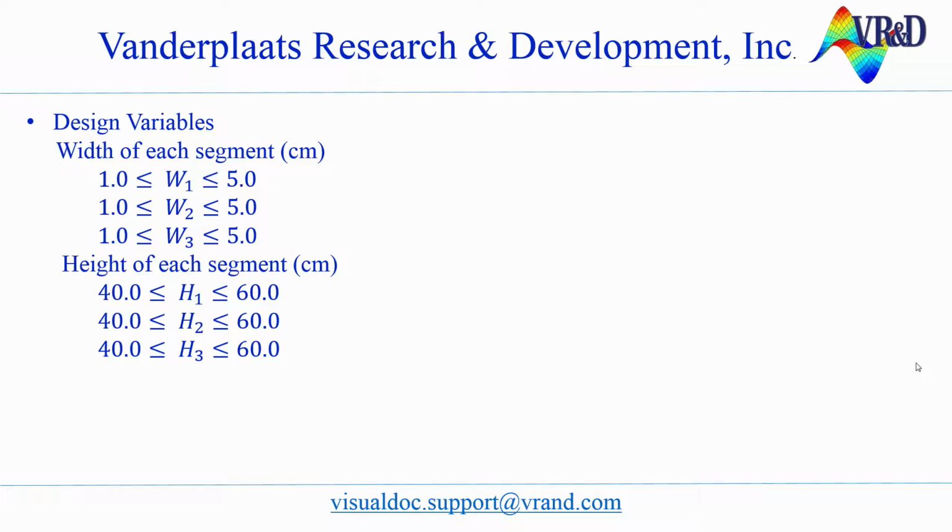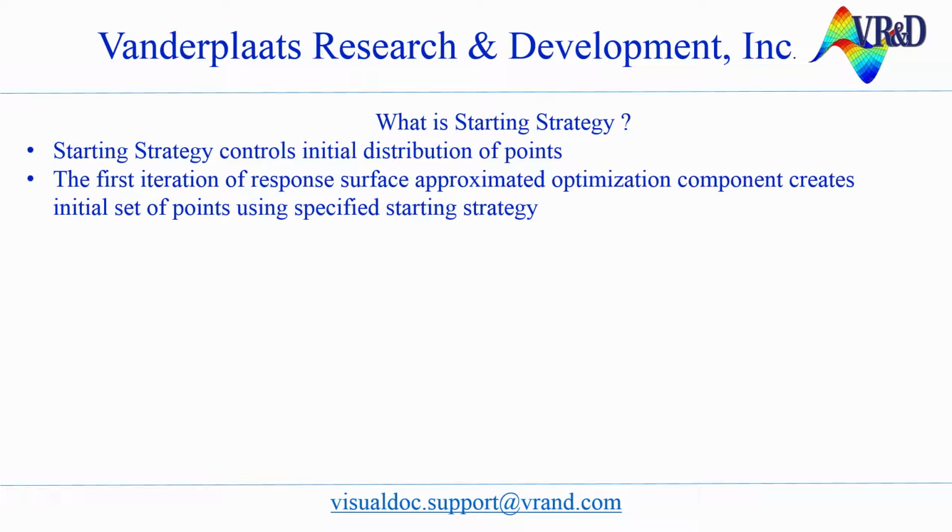Now, first we will create design points which can be used as the initial set of points for the starting strategy. The starting strategy controls the initial distribution of points. The first iteration of a response surface approximated optimization component creates the initial set of points using the specified starting strategy.